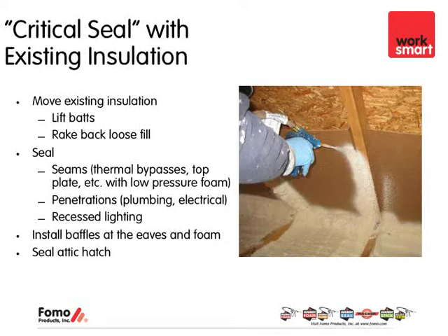You also want to be able to install baffles, and what the baffles allow is for the soffit and the ridge vent to be able to work properly, to be able to move air through the attic so that you prevent any moisture condensation, etc. In this case, you want to be able to actually take foam and make sure that you can air seal those baffles as well. And you certainly want to address any attic hatchways and make sure that the attic hatchway is sealed properly so you don't have air leakage coming from, again, the first or second floor coming up through the attic hatchway.